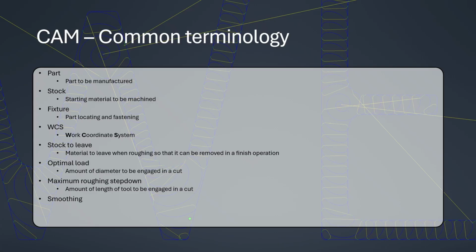These amounts of points, sometimes millions, can overwhelm the CNC, meaning that it's going point to point and pausing on each point very slightly. But that means that in reality you're not getting the specified feed that you want, because it's doing stops all the time. What smoothing does is try to apply curves to the points, and it tries to minimize the amount of points that you have in your code.